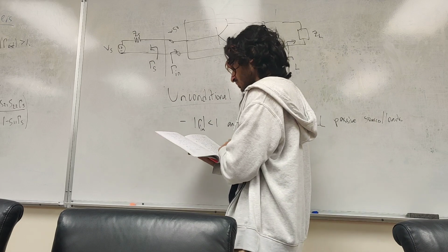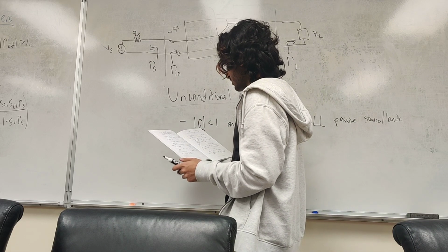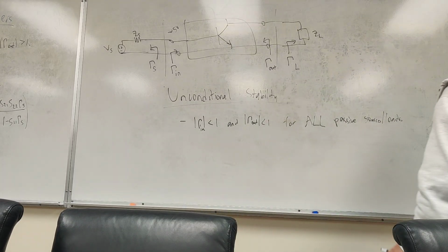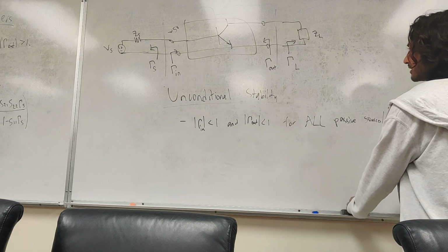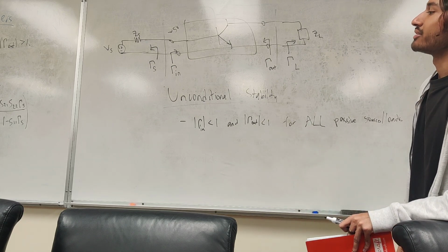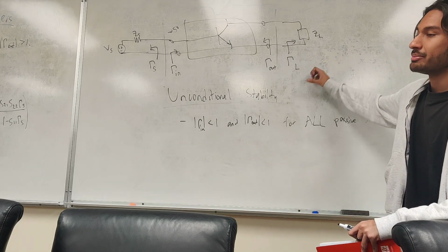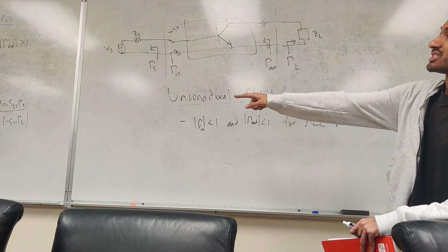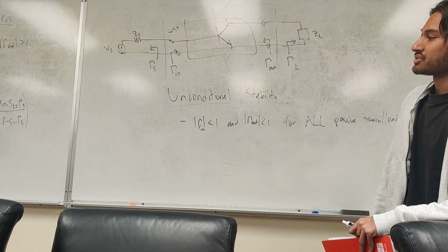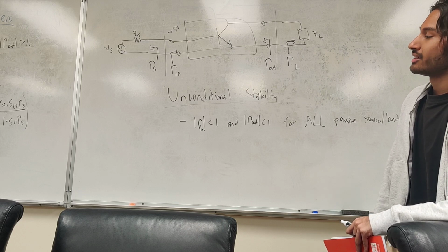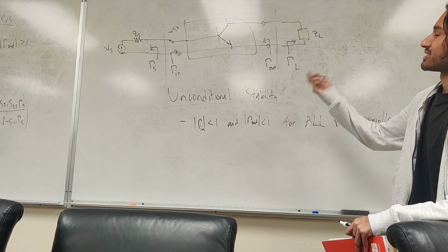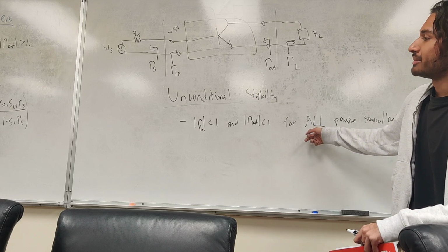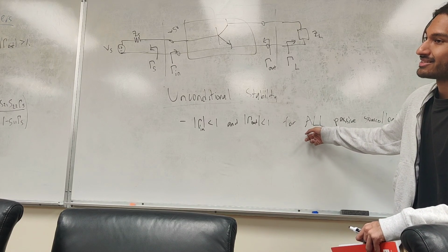So, this is where it gets trickier. We have a lot of variables here, right? Assume that when we have a certain BJT, the manufacturer gives us the S parameter file, so we know S11, S22, S12, S21. That helps with some of those equations. But we still have two unknowns, gamma L and gamma S, right? How do we figure those out? Those are based on whatever ZS and ZL are, and we're saying for all passive networks. So are we going to sit there and do the math for an infinite number of possibilities?